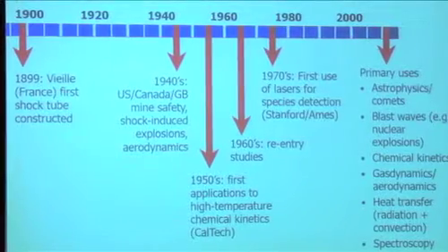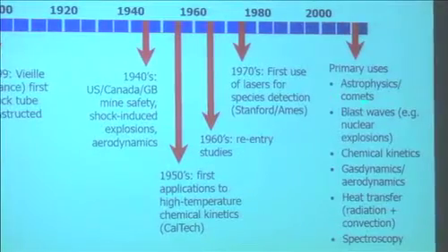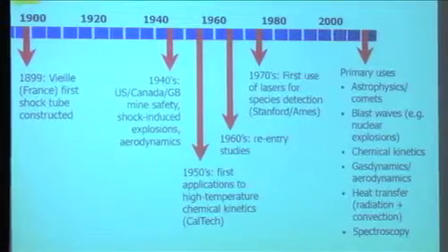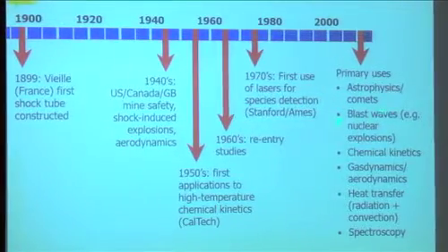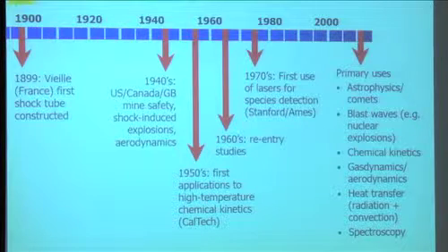You can use these to study, say, spectroscopy. Maybe you're interested in, in fact, one of the people that I know was interested in the spectroscopy of comets. You might be interested in looking at blast waves. So aerodynamics, chemical kinetics, heat transfer. There's a lot of reasons why you might like to have these high temperature flows. Now, high temperature is high enthalpy, so you also can have a nozzle in the end and expand that high enthalpy gas out into a hypersonic shock tunnel, and that's how really high Mach number flows are created in the laboratory using shock waves.